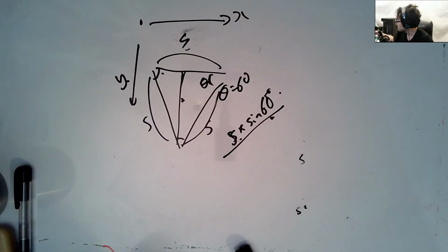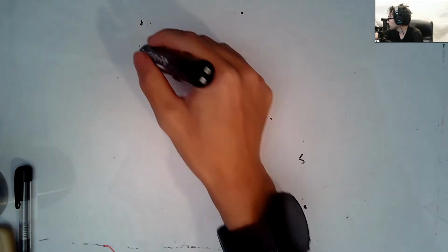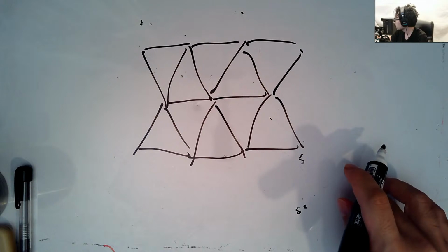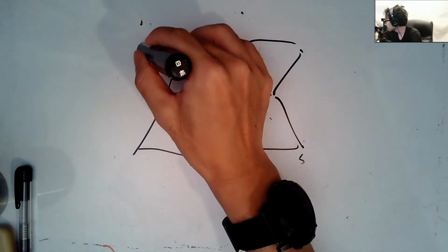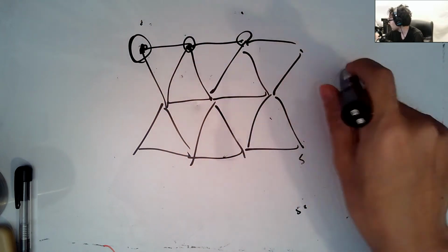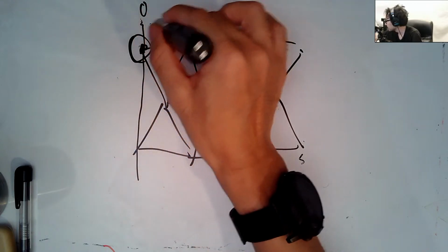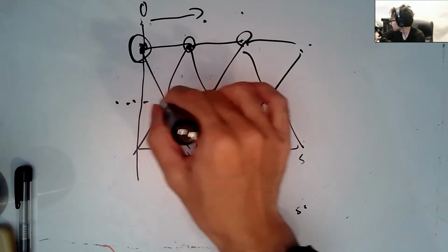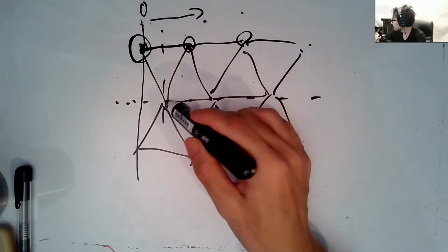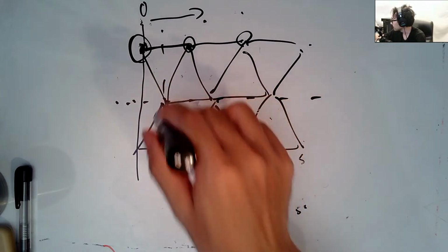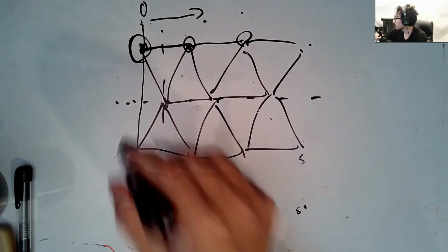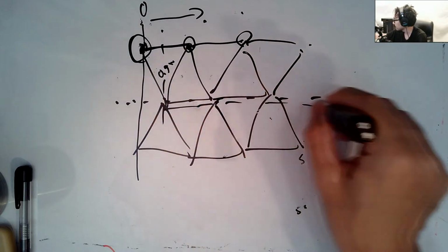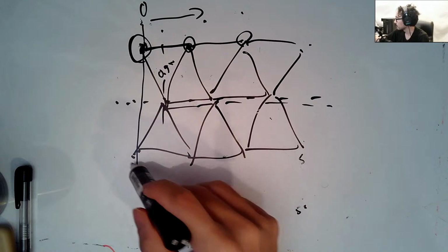That is because if we have a triangle tile like these, you probably can see that the point positions, these are the positions that I'm trying to create right now. And let's say this starts from 0 on the x direction. For the first row, it starts from 0. But then from this second row, it starts from half the size of this edge. So you need to define this offset for each even row number. For even row number, it starts from 0.5 multiplied by size, then go like these. Then if it's an odd row number, then it starts from 0 again.